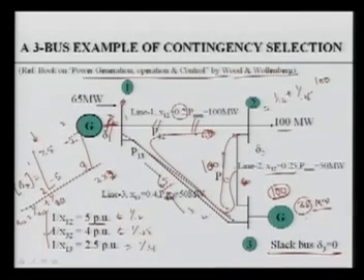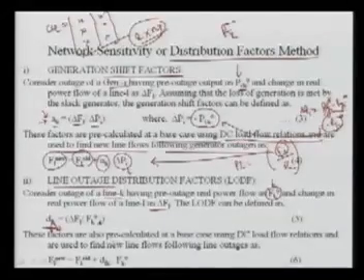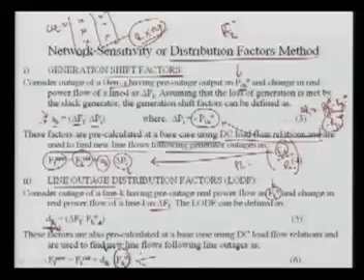So we can define the line outage distribution factor, where L denotes the lines where it is flowing and K is due to the outage. So it is the change in L divided by Fk naught, and that's defined here. Similarly, we can calculate these values again and then use these factors. Knowing these factors, with any change in the line power flow, we can get the new power flow, and then we can calculate the PI value and the performance index very clearly.